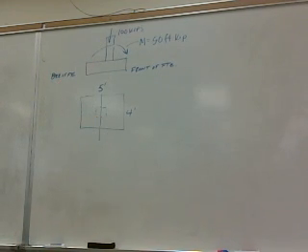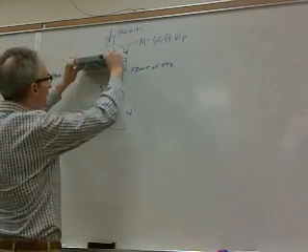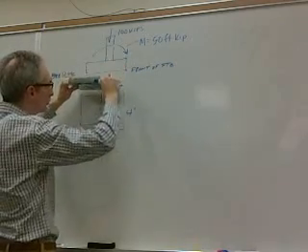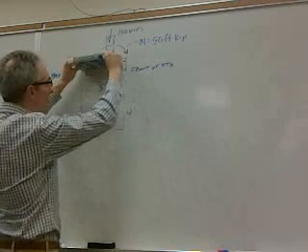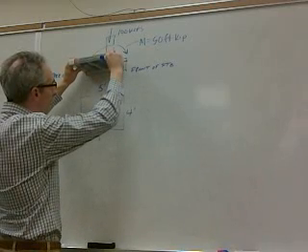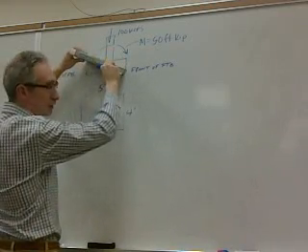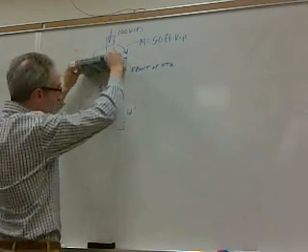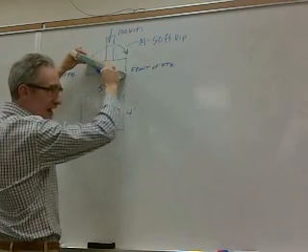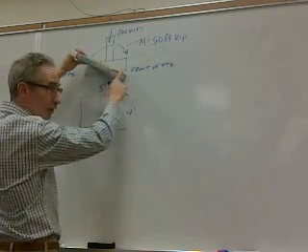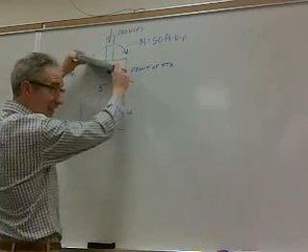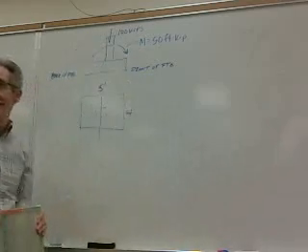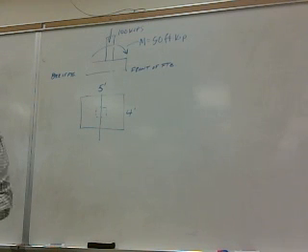And what this means is, you can imagine this footing, the 100 kips wants to push this footing down into the ground, but what the moment wants to do is rotate the footing. Okay, so it's really bending the footing almost like a beam, bending the footing down into the soil over here on the front side and actually wanting to lift it up on the back side. Okay, does that make sense? So a very common application of combined stresses is this type of an arrangement.